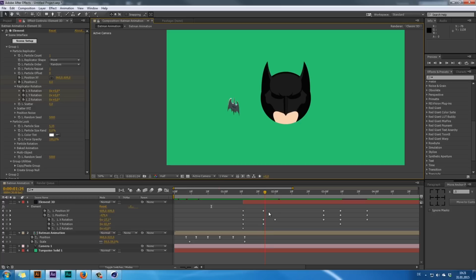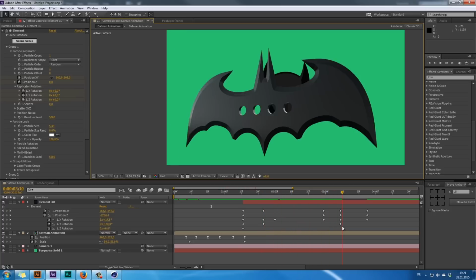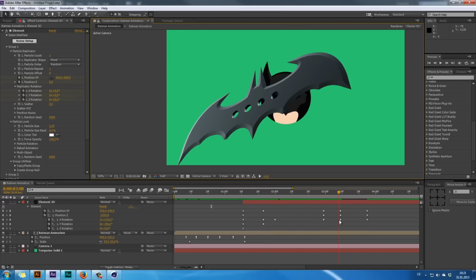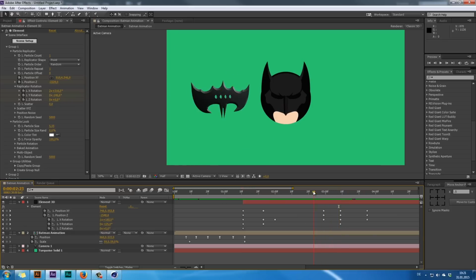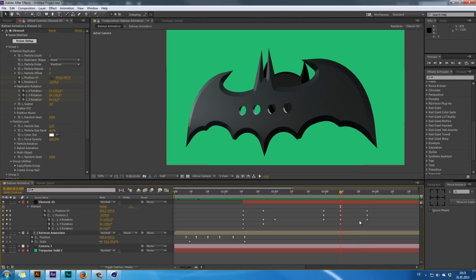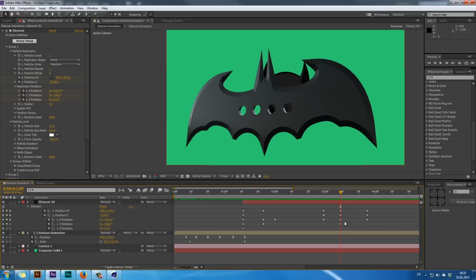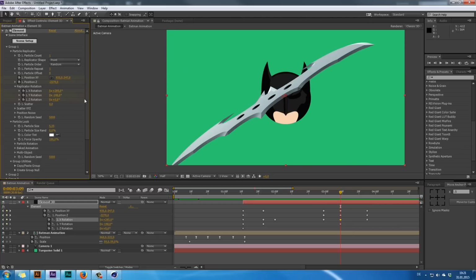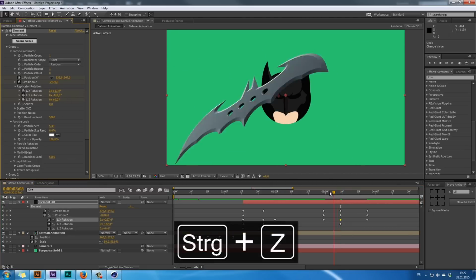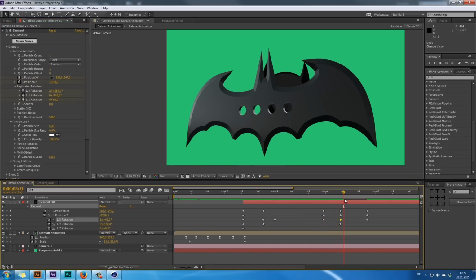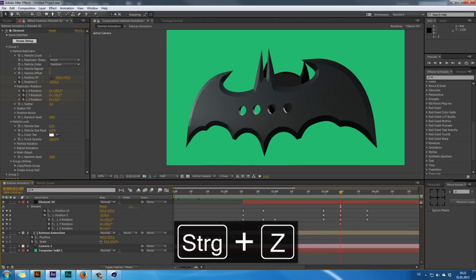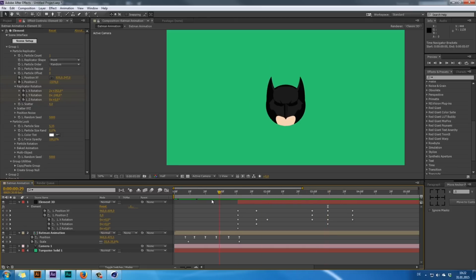As you can see, it flies in, then the shuriken comes, animated out, flies around. And what I just did to create this kind of slow motion effect, where it's coming to the front right here and then comes a little slow motion effect, is that I've made the rotation of it a bit slower. I made a keyframe right here and didn't crank this all the way up. I just made a small change so it looked like it flew in kind of slowly, and that was the basic magic behind the slow motion effect. Because some of you guys contacted me on Facebook to ask, wow, how do you create Element 3D slow motions? And it's just some basic keyframe work.